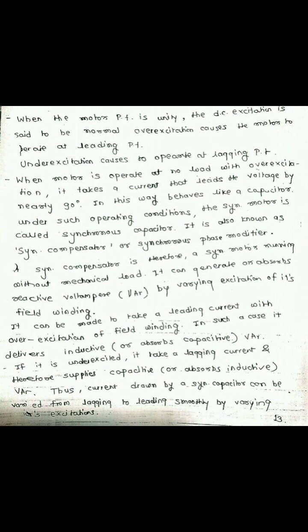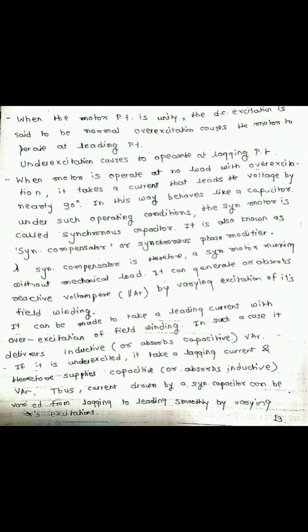The synchronous compensator is therefore a synchronous motor running without mechanical load. It can generate or absorb reactive volt-amperes, that is Q, reactive power in kVAR, by varying the excitation of its field winding.